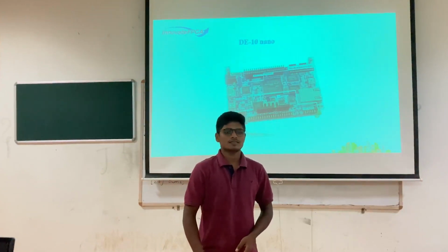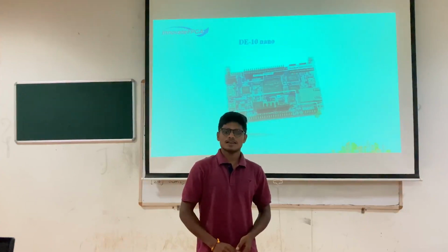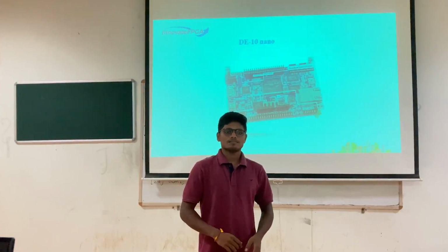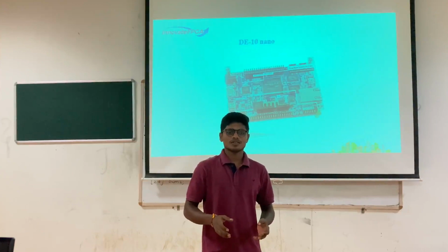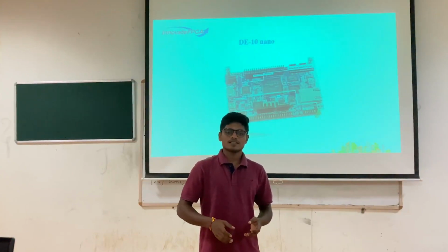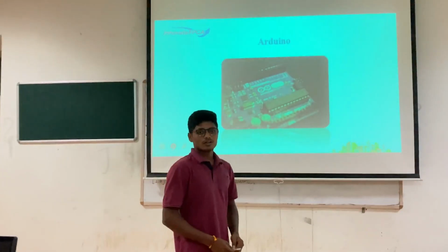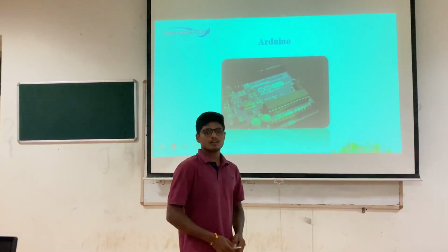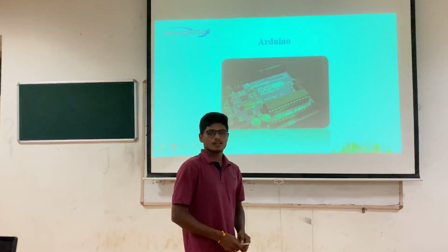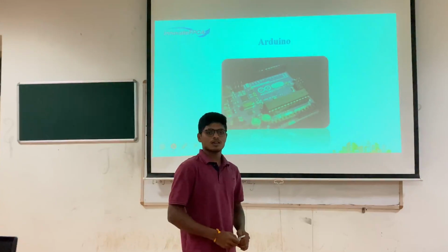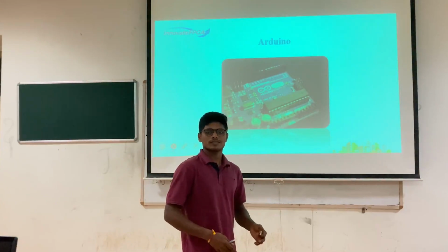For that, we used a pre-installed image, and we modified the system on chip raw binary file using the existing XFCE version. We use an Arduino Uno microcontroller to collect all the analog sensor data, and we send all the data using serial communication to the DE10 Nano board.